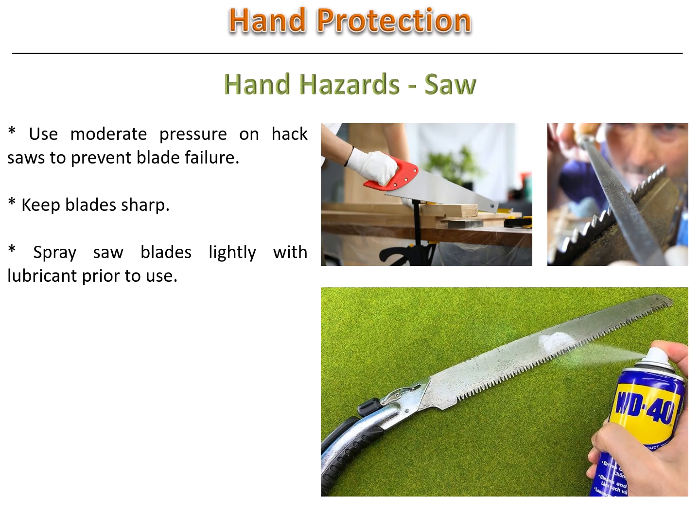Hand hazards, saw. Use moderate pressure on hacksaws to prevent blade failure. Keep blades sharp. Spray saw blades lightly with lubricant prior to use.